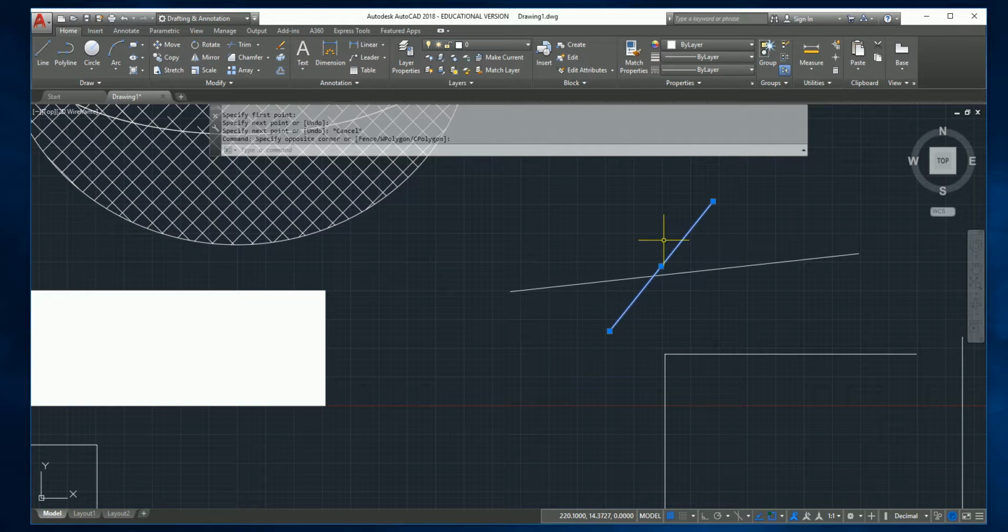So again, it happens to do with a lot of selection. Then also when you get into plot styles, if you have a certain line that's set to print gray instead of black, if it's behind the black line, it's going to print black. If you put it to the front, it'll print gray. So there are different things you might have to do that with.